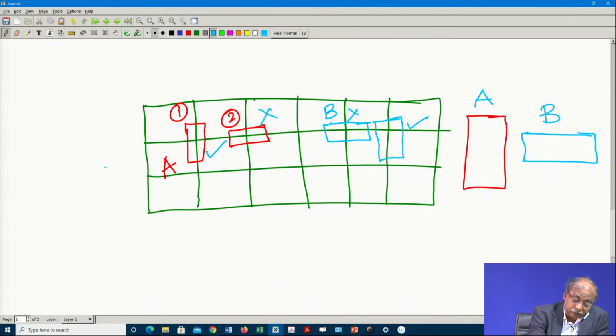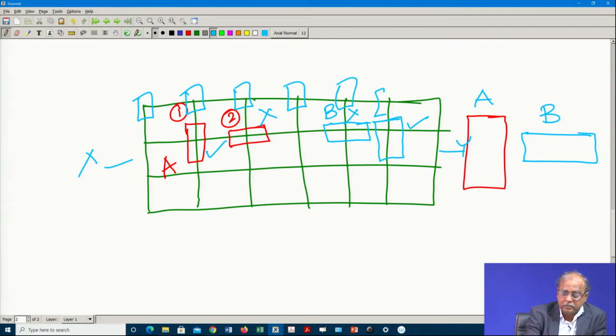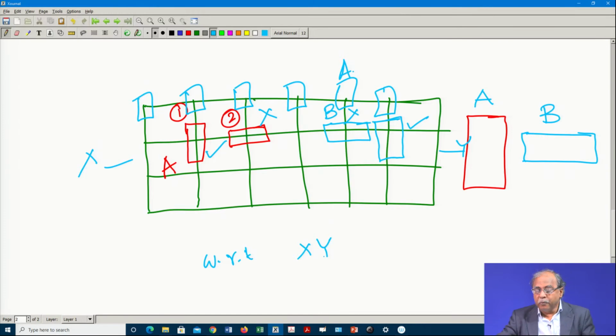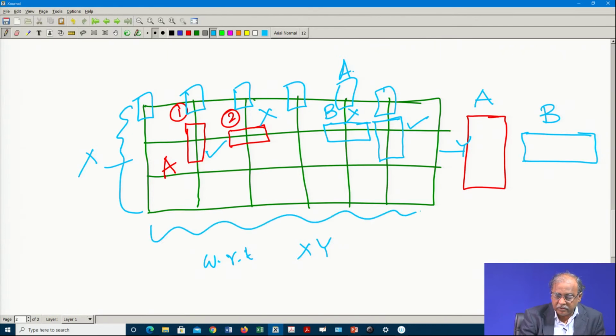because whenever you are taking moment, say for example about x and y, of different columns, then with this orientation, that orientation will be A, and only with respect to x and y the moment of resistance will be more, because here the width is very less, but here the width is very more. So, we always provide the column dimension in this particular fashion.